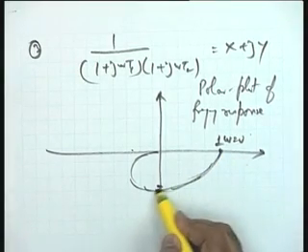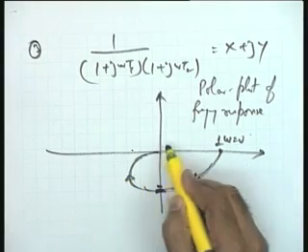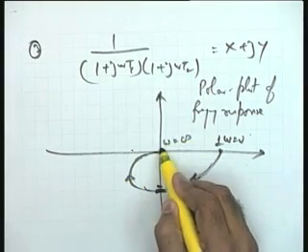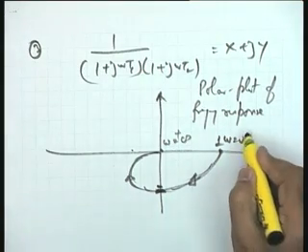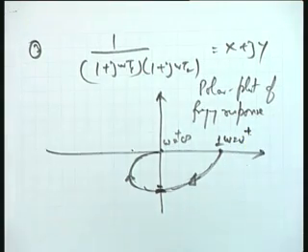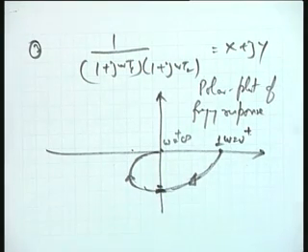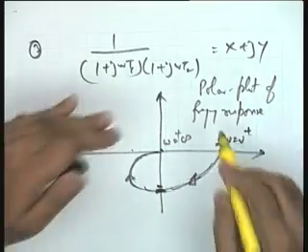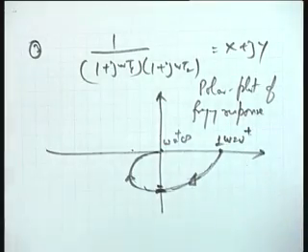These magnitudes I leave to you, you can easily calculate, and this is good enough, you see. Make omega equal to plus infinity as the point, because I am going to take the mirror image, and let me take omega equal to 0 plus because of the requirement of the mirror image, please. So, omega equal to 0 plus and omega equal to plus infinity are the points, and this is the polar plot of the frequency response I have got.